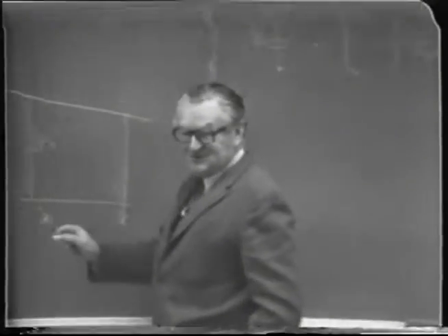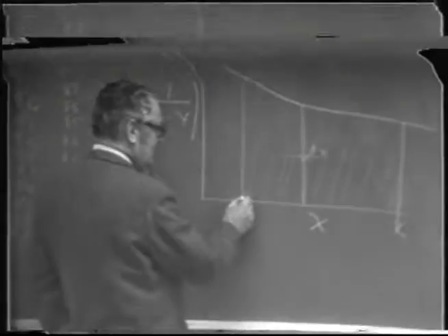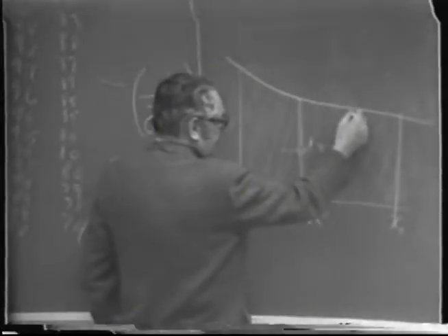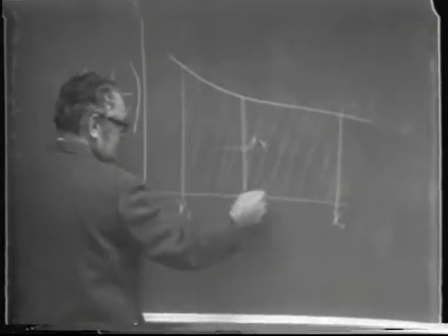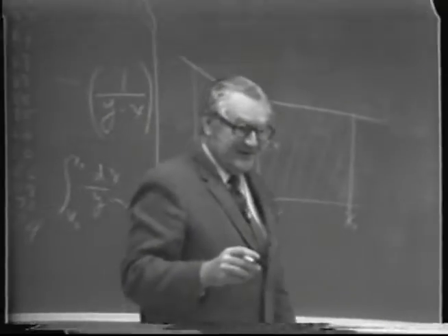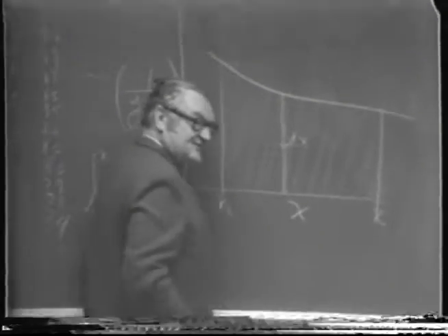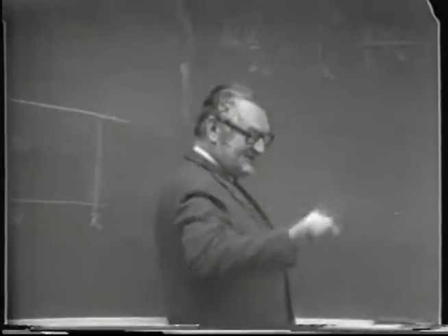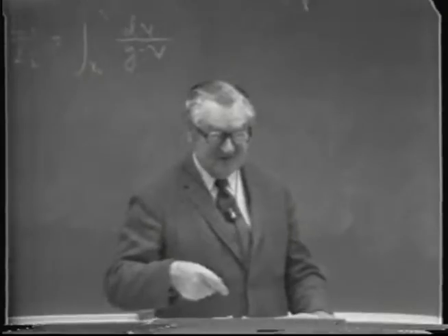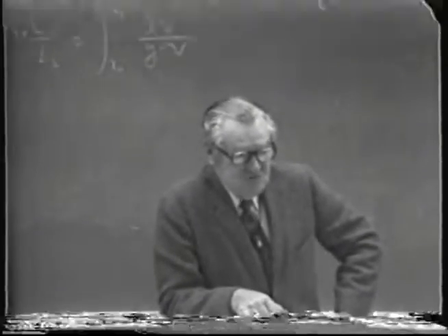But it's a little device where you roll it carefully along the paper, and the little roller, as you trace the curve from start all the way back to the origin, will count up the area in reference to, let's say, some other designated area. So then you get the fraction of the curve by just tracing it carefully along. It takes a little practice to use a planimeter, and you have to check it to make sure it didn't slip on the way, or a few things like that, but it can be used.